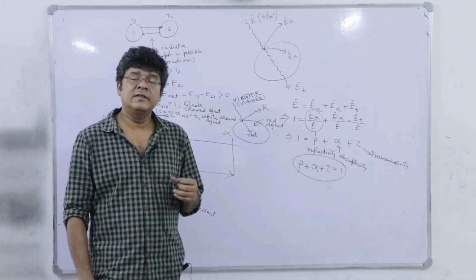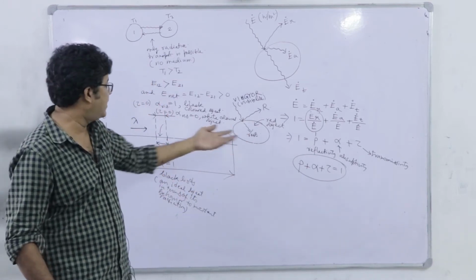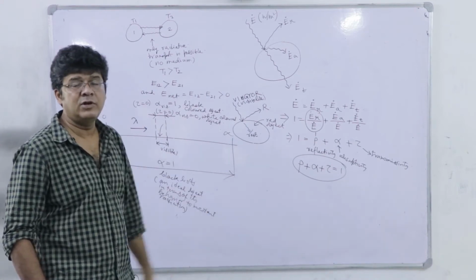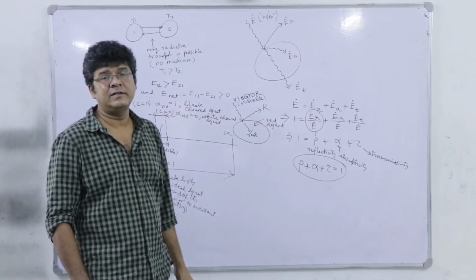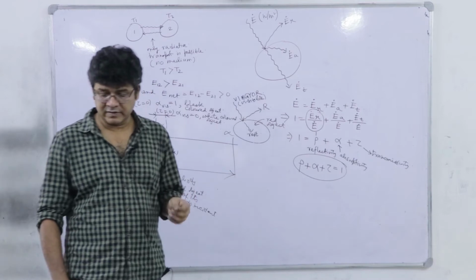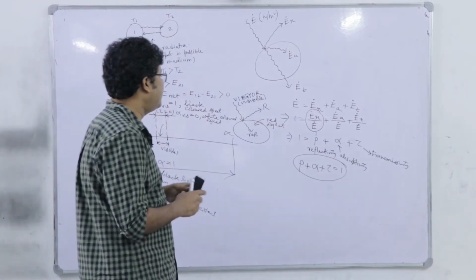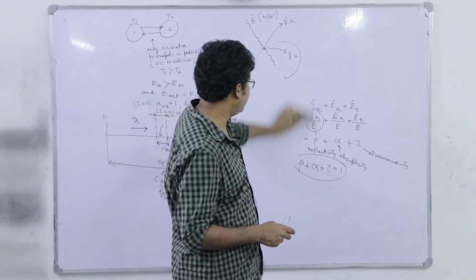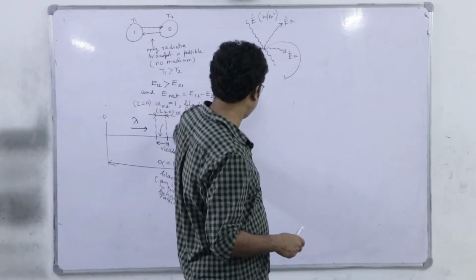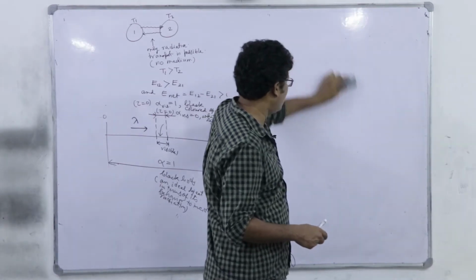and here we will do it, we will see later that here we will do it in terms of something that is the absorptivity, where absorptivity of this black body is equal to 1, and also we will actually carry forward our analysis of this type with another parameter called emissivity. So we will discuss about it, right. So black body has got a defining property that alpha is equal to 1, right. Rho and tau will be equal to 0. Tau is definitely equal to 0 because most of the objects are non-transparent or opaque.